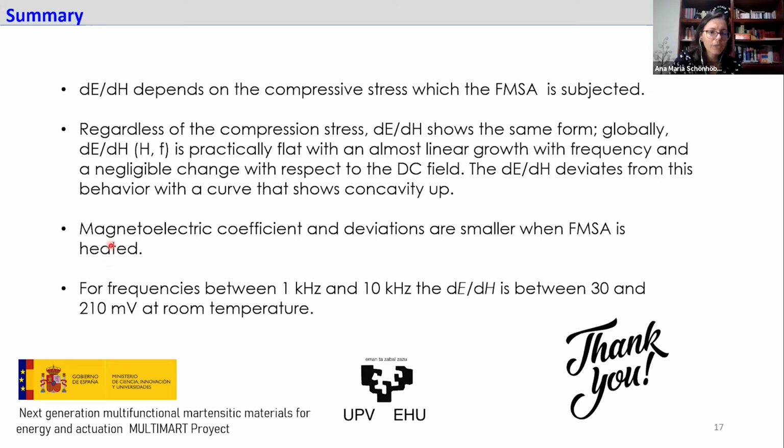The magnetoelectric coefficient and deviations are smaller when the ferromagnetic shape memory alloy is heated, and for frequencies between 1 kilohertz and 10 kilohertz, the magnetoelectric response is between 30 and 210 millivolts at room temperature.